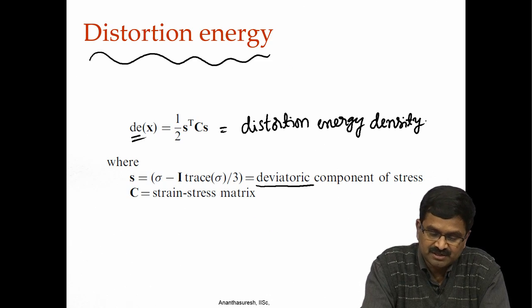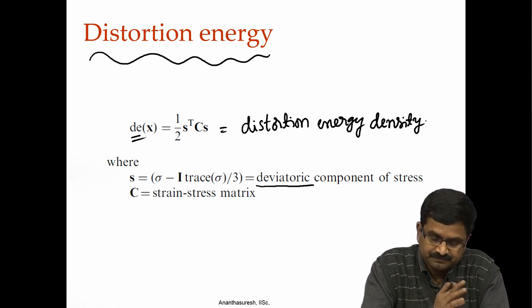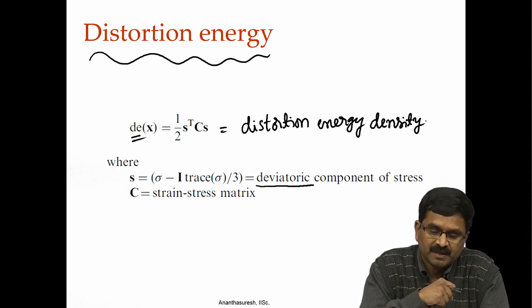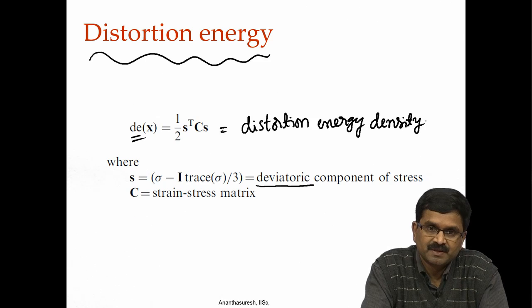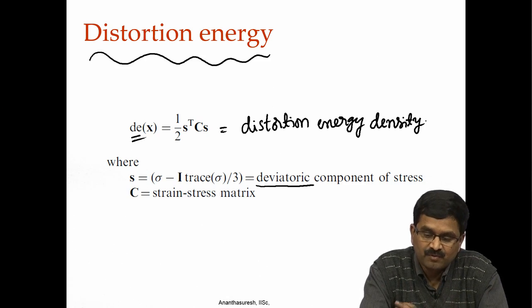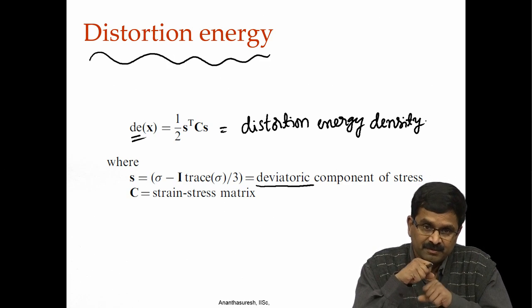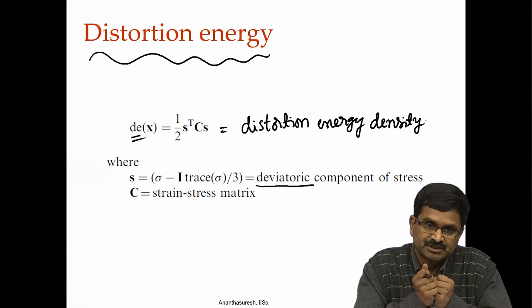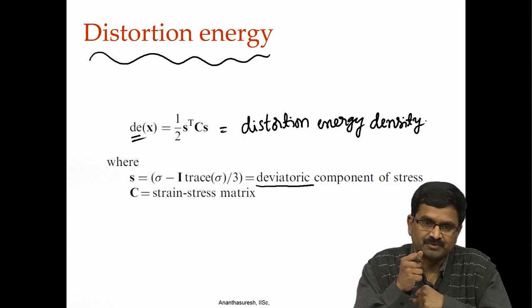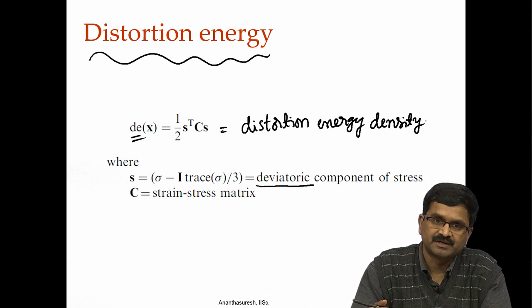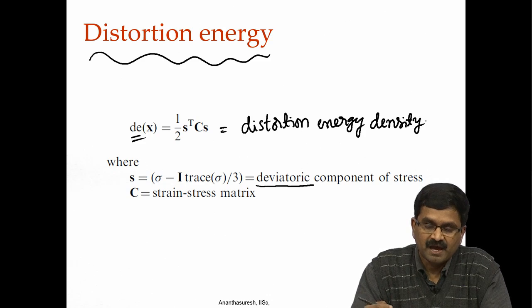If we have this distortion energy, the idea is that when things are excessively stressed, and there is going to be shear, bending and all that, if we minimize the distortion energy, can we get... Because strain energy we already have put, we are trying to minimize strain energy, and that is going towards rigid body linkages. What about putting distortion energy? That is, we do not allow the elements to distort in terms of their shape, but they can stretch if they want to. That is what we are subtracting this component, because this is what causes the actual failure in